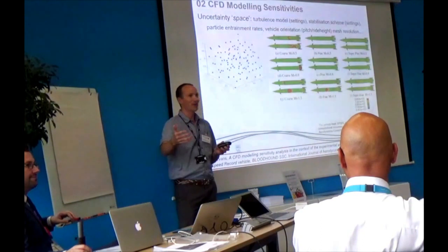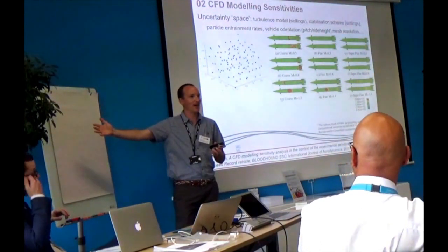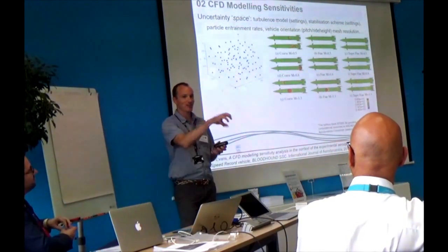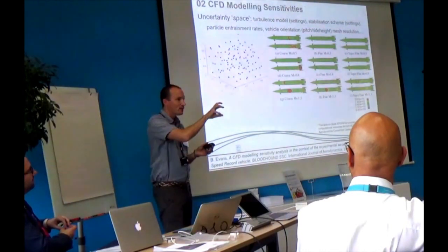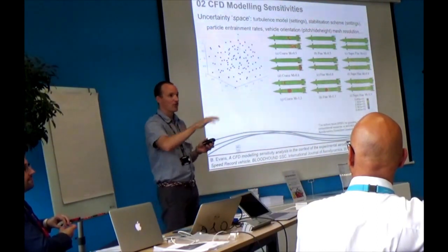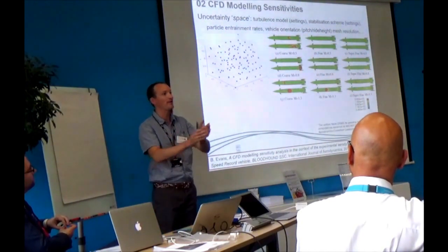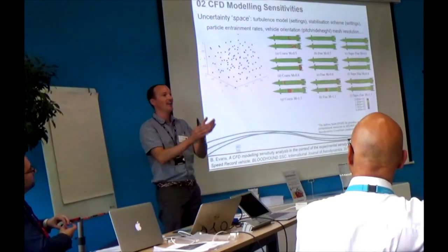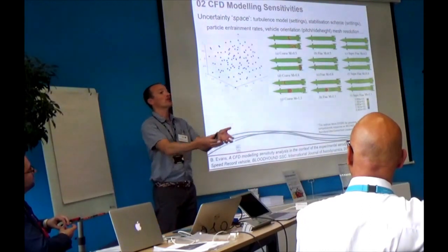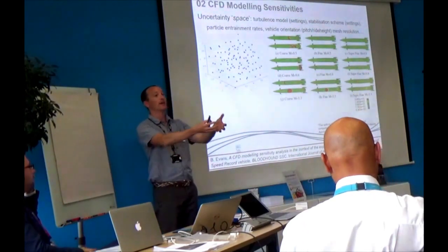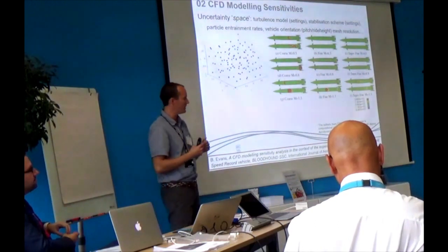Now, in the real world, where you're putting your friend in a 1,000 mile per hour car, you do the complete opposite. You cluster your sensors in regions on the surface of the car where this sensitivity analysis is showing that at these positions we have the greatest level of uncertainty in the modelling. And that's where we want to learn as much as we can, therefore that's where we're going to try and glean as much data as we possibly can.